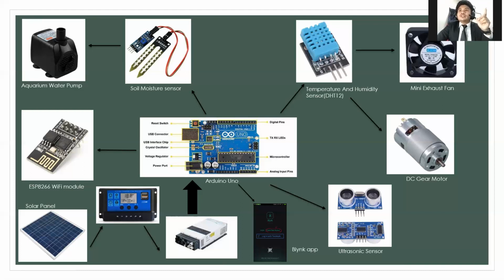The charger controller, also known as a charge regulator, regulates the voltage and current going to the battery from the solar panel. Then for the solar panel inverter, the variable DC output of the photovoltaic solar panel is converted into utility frequency alternating current, AC, that can be supplied into the commercial electrical grid.